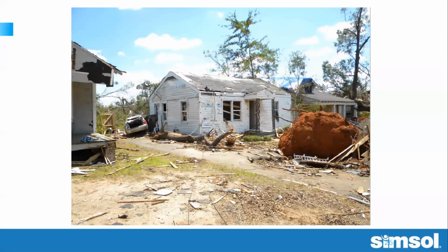Now let's take a look at this photograph. It's a little bit different. Notice the vegetation. We've got an uprooted large tree on the right side of the photograph. Look at the wind profile of the damage to the roof that you're seeing. You've got a lot of shingles missing, primarily at the ridge and the gable end along the eave. Look at that parking job of the car to the left of the little house there. Looks like that fella had quite a rough night if that's where he left his vehicle.